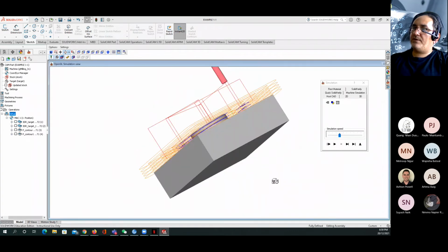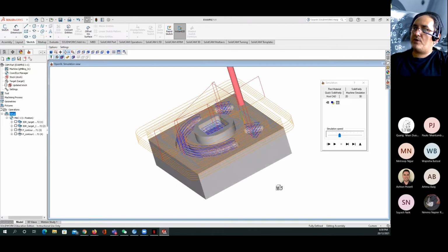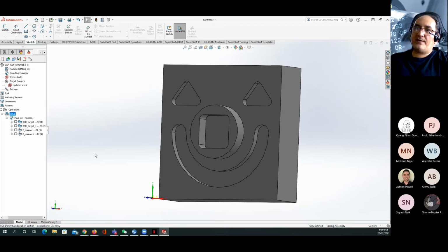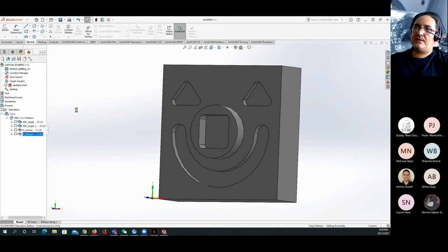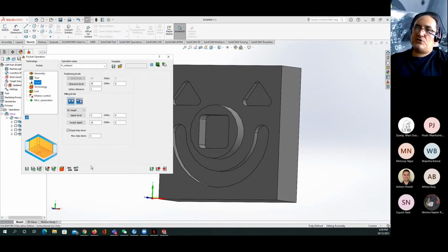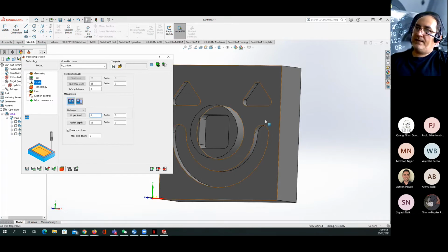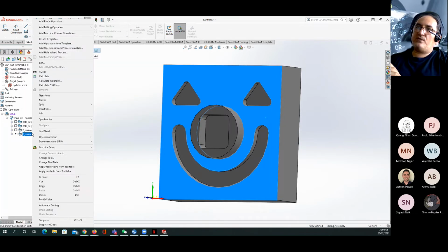Okay, I have something wrong here because it starts to cut in the air before it starts to cut the pocket. So I will fix that before I make the final G coding. So I will edit this operation because this will be very important. We're talking about the levels. So the upper level here is not going to be the 0. I'm going to click here and click here. So it's going to start from -10 to the depth of the 5 millimeters. Save and exit. Do the calculation for this operation.